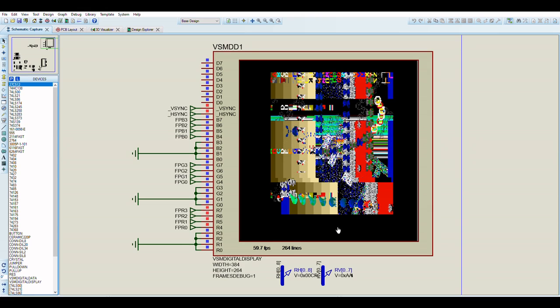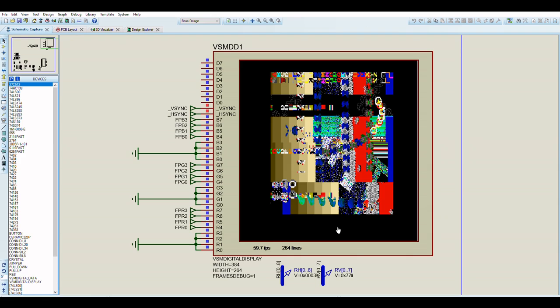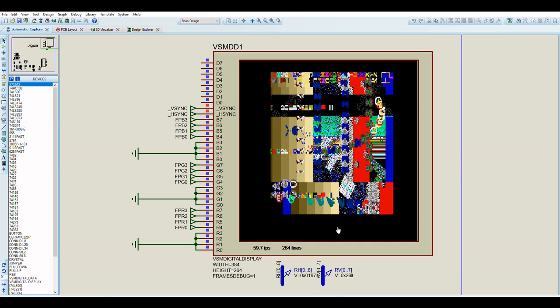So all in all, modern software tools like Proteus really do pay for themselves, because I can do all of my simulation on this board, in this simulation software. I can debug all of the timing in the simulation software. Each of the memory chips and everything is configurable with nanosecond timing, and I can tell Proteus whether or not I think the RAM has to be fast or slow or whatever, and I can search for the bits on my router, and I can verify that the RAMs have this timing, etc., etc.